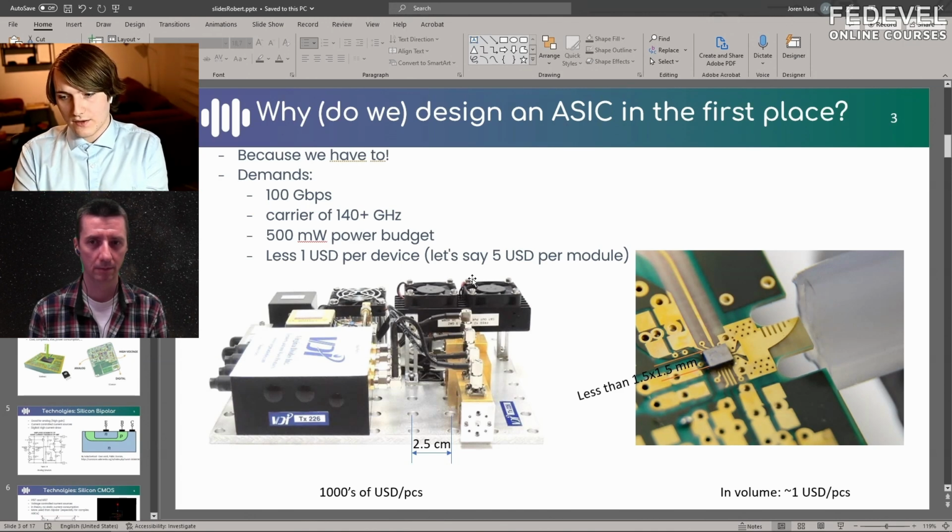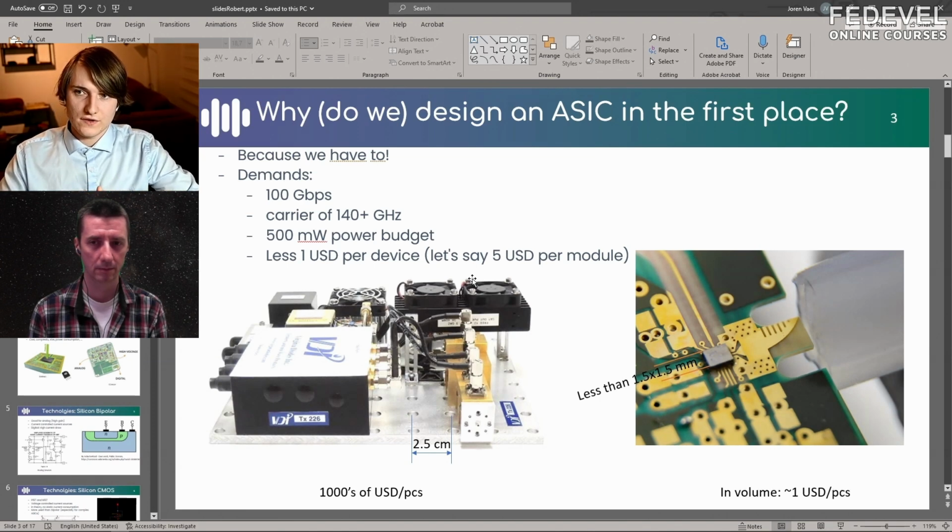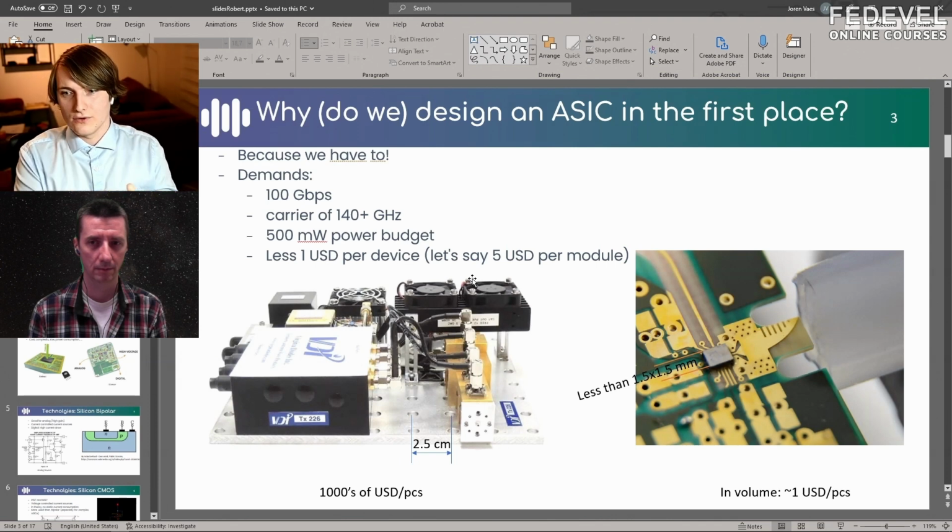And then there's also engine noise, which can be an issue for copper communication. Spark plugs, or in electromotors the rotors and the high pulsing fields, have frequency content that is very low compared to what we do. So it might be an issue if you're trying to use a coaxial cable, but for us there's no spectral content at 140 gigahertz, so we can almost ignore this.